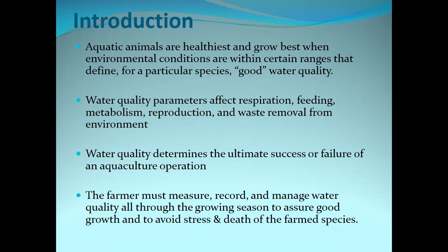Record keeping is very critical, and you can use the records in case you have a problem within your system. You can go back and see when your parameters were starting to go out of balance. If you keep good records and know exactly when your water quality parameters started to go out of range, you can troubleshoot more easily. You can look at your system now and go back and ask, what happened differently during this period of time?